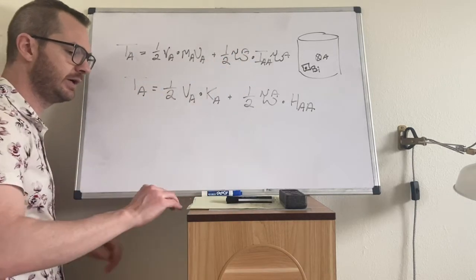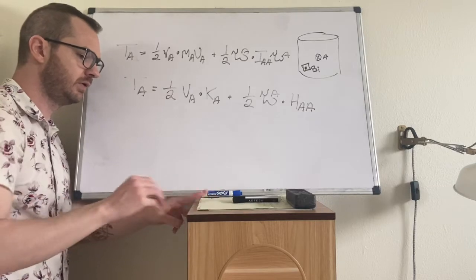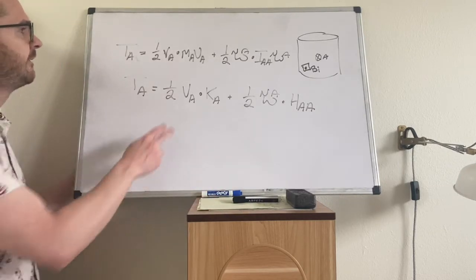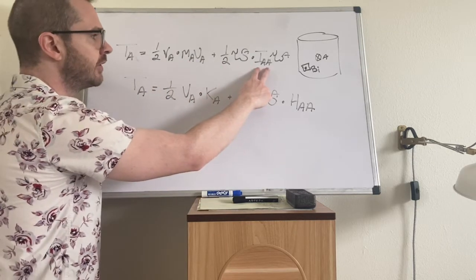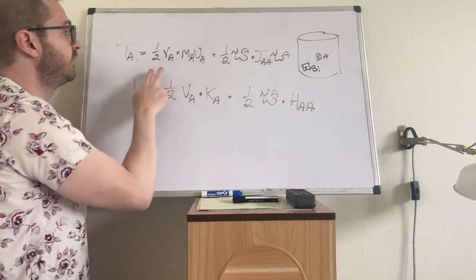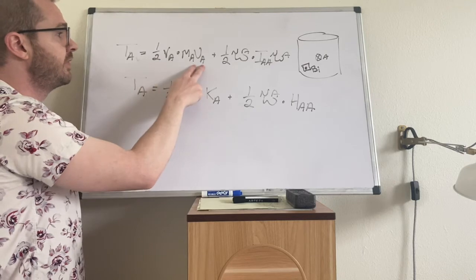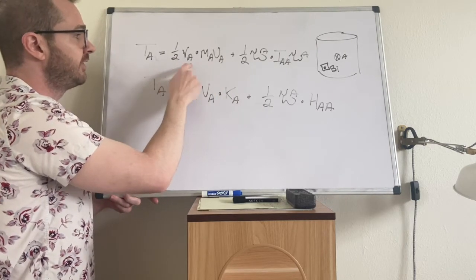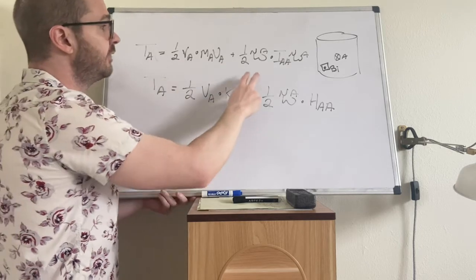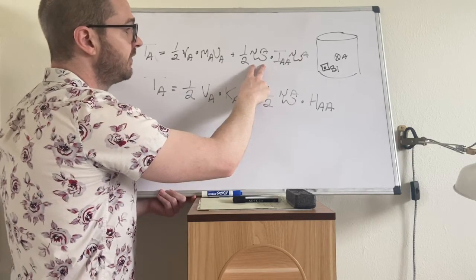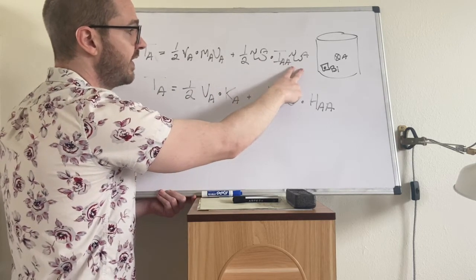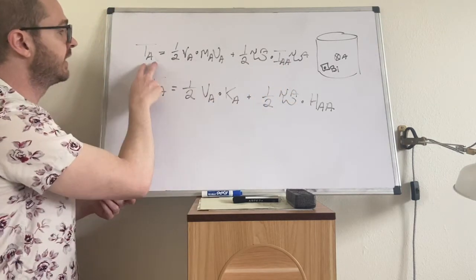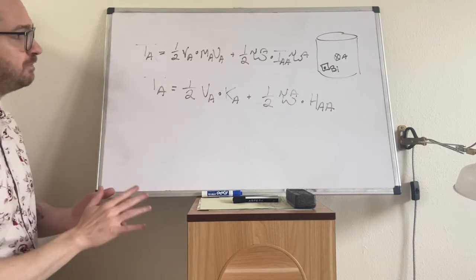So if you're not changing mass, if you're not burning fuel, anything like that, then your mass and your inertia are constants, and you simply find expressions for the velocity of a body. You can dot those two velocities together to get a scalar. You find the angular velocity, you dot that with inertia, and then that's multiplied by angular velocity again. And from both of these, you get a scalar energy quantity.